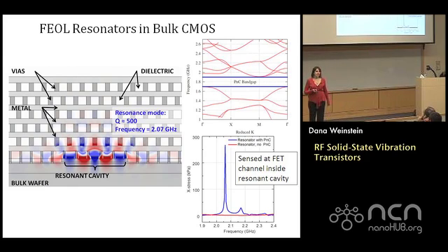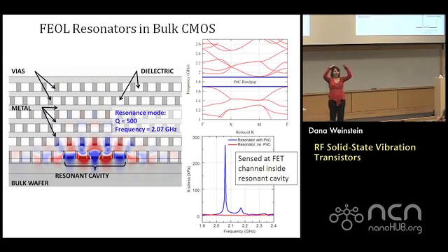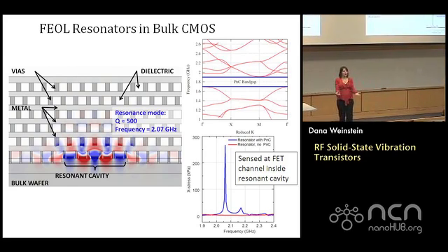The answer is leveraging what's above you. I can't really do anything in terms of what the CMOS stack has to offer me underneath the transistor. It's just silicon. And if I'm not careful, I'm going to be driving these acoustic vibrations with this capacitor, which is the gate dielectric, and I'm just going to be launching these waves straight into the substrate and losing half my signal even to start with.